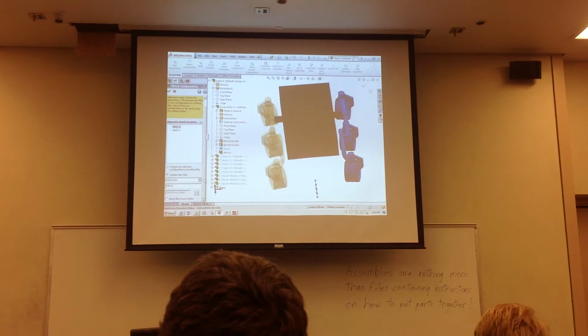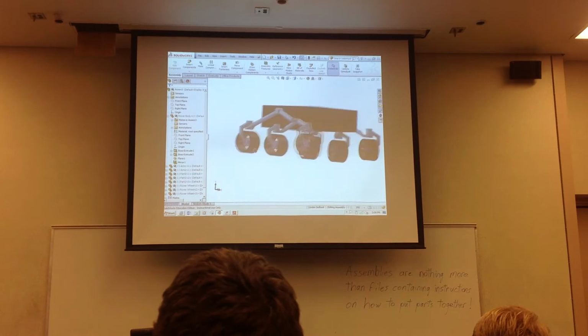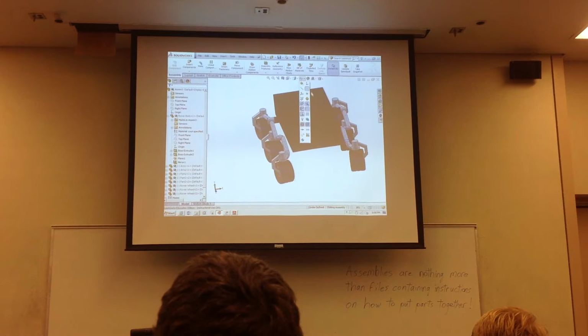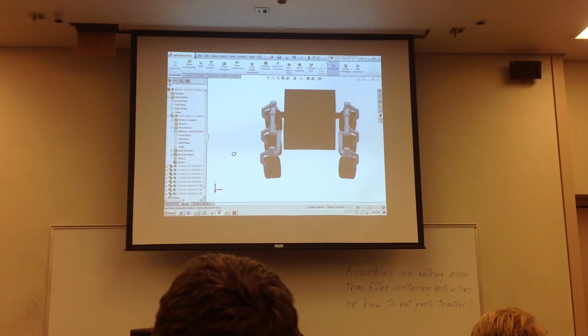Well, that's fine. We just have to tell SolidWorks, okay, create new files. It's going to add the prefix mirror to the original part names for these parts that it's created. So that's all fine. We can just click the check mark and SolidWorks does its job, and we end up with the mirror components just like we want. Let's turn off these temporary axes because they're just getting a little bit cluttered.